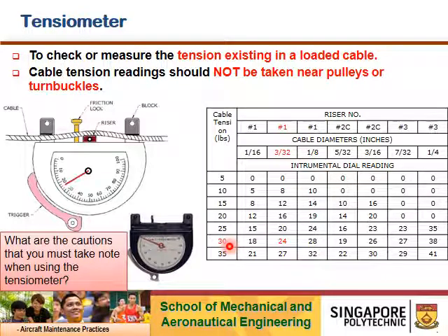Depending on whether it is in the range, if it's in the range, you don't need to adjust. If you fall short, you need to adjust, using the turnbuckle to tighten or loosen the cable system. Most of the time, it doesn't give you a direct reading, so make sure that you do not read directly. It's not 24 pounds, but you need to use the chart to convert.